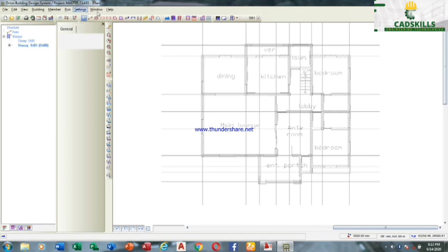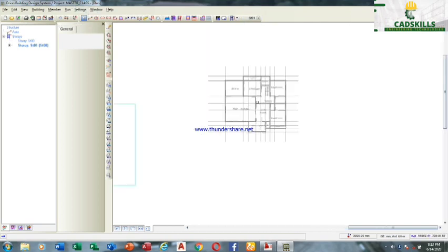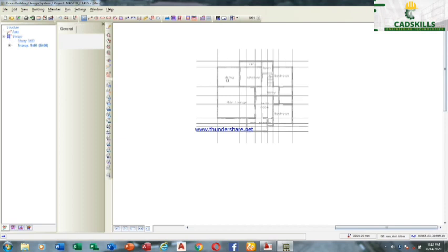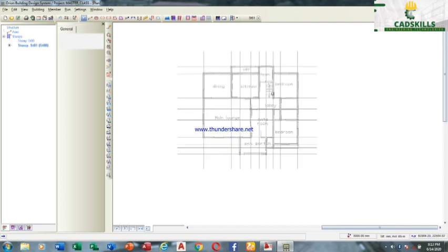Now these are the tools that we're making use of. All these things, all this drawing and all these lines, they are inactive in this environment. They don't support our normal layers in AutoCAD. So we are to trace everything that has been done here with replacement of Orion properties. Is that all right? Now, Orion properties, the grid lines, the columns, the walls, and everything will be replaced. But this is going to be a guide to aid our work. Therefore, it's going to be easier.